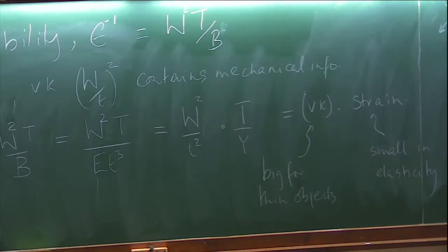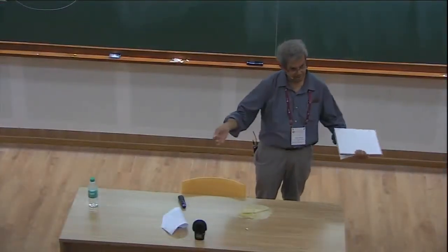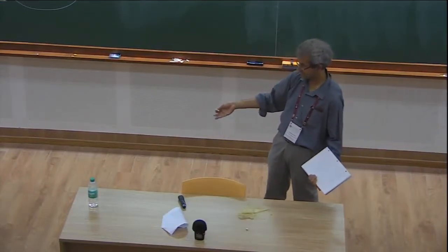This number can be anything, is the point. I think it immediately forces a realization that there are limits to this equation to think about. There's a large bendability limit and a small bendability limit. The thin plate equations are perfectly valid for both, but they have completely different behavior.